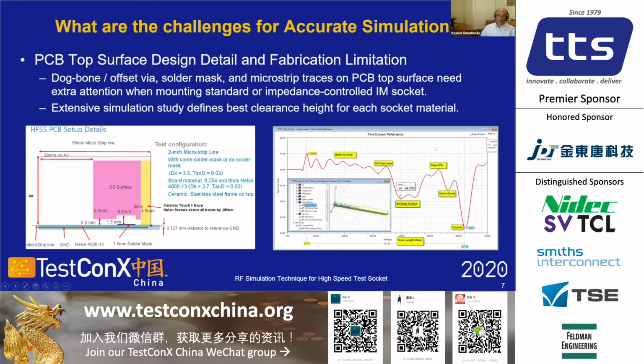So the next slide will show what we did. We modeled a two-layer PCB board with microstrip trace and with reference ground on the second layer at the bottom, with FR4 material, and tried to optimize this design to get a perfect 50 ohm impedance plus or minus 1 ohm using transient circuit analysis.